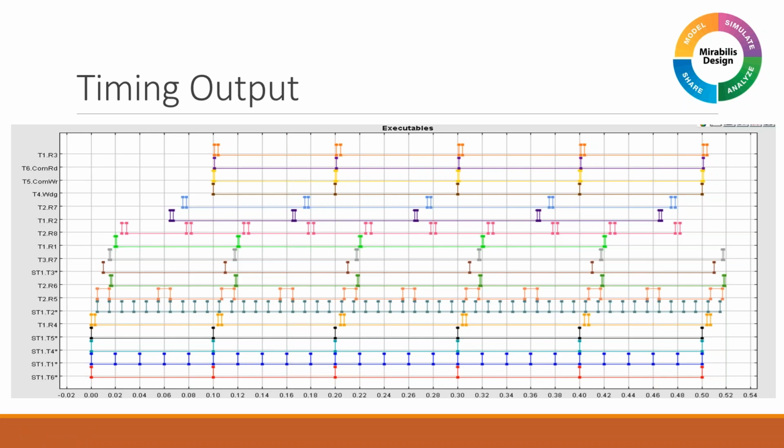So for example, if I take one of these things here, say this runnable 6 over here, notice there is this one over here, and all of these tasks are not able to start because of the duration of this task. As a result of this task executing, these are all getting delayed, and that could relate to the timing deadline misses that you are having in your architecture. So it actually helps you trace what is the cause of the failure. It's not just about, yep, something failed, but rather you can track it backwards and see what really caused the failure.